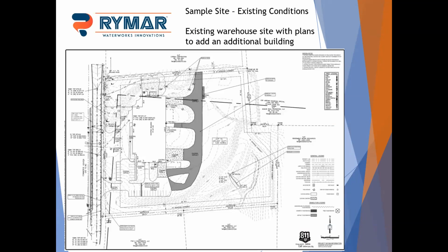For this, we're going to look at a sample site that was a project done in Greenville County, South Carolina. For those not familiar with SedCAD, it is a software that was developed for use primarily in mining. It does sedimentology, and depending on the MS4 you're at, some will accept a SedCAD sediment basin design over a more empirical volume-based design.